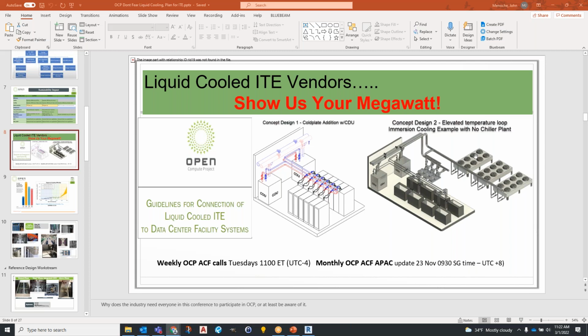However, when you look at it from a structural perspective and you take into account the clearances around that equipment, the aisle widths and so on and so forth, we're down around 150 pounds a square foot. So if part of this conversation is that every one of these solutions has a different footprint, a different wet weight, and different clearance requirements, what is the range of actual floor loadings that we see from these solutions today? Because if we just tell them 500 pounds a square foot, I guarantee you every place that's getting built to 500 pounds a square foot is being severely overbuilt.